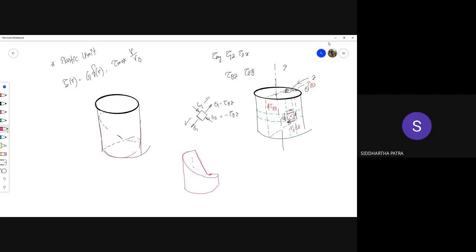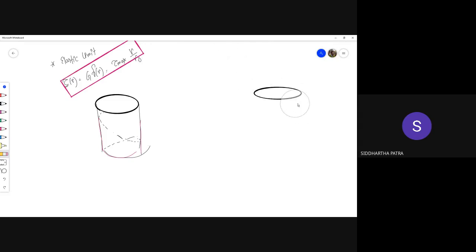But we need this expression where we can relate between the shear stress and the radius, and that is valid within the elastic limit. But you'll have to again relate that to the torsion applied to the system. It's a known exercise. You already know the final expression that tau max for a solid cylinder is 16T by pi d0 cube. But I'm not going into that. I'll be going into that, but through the derivation.